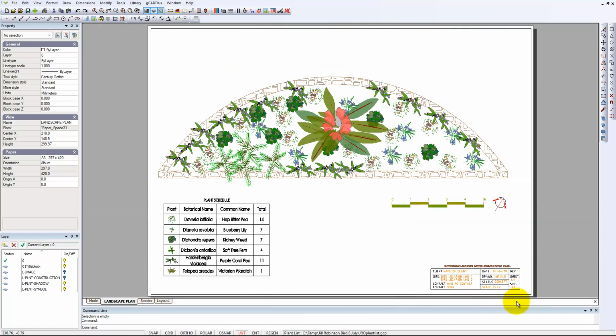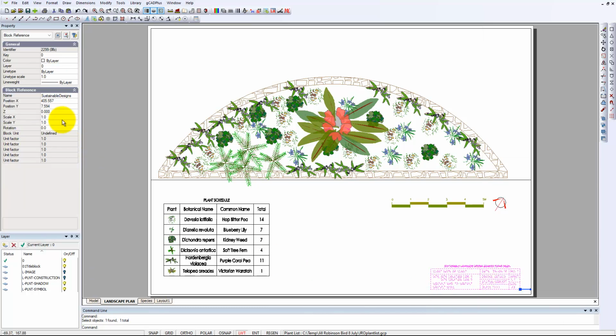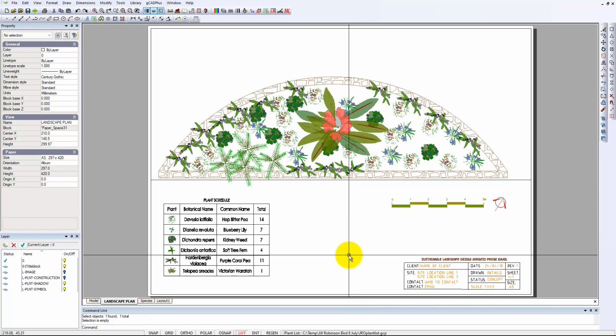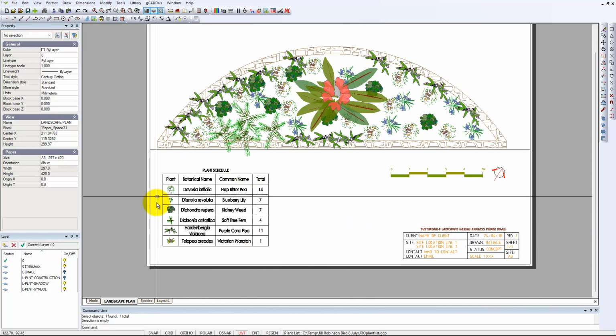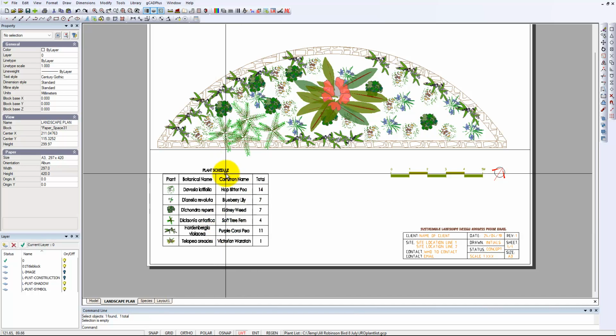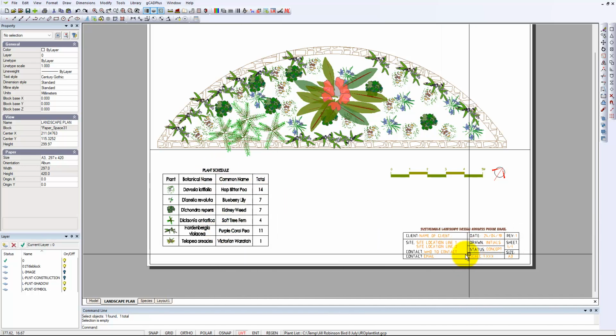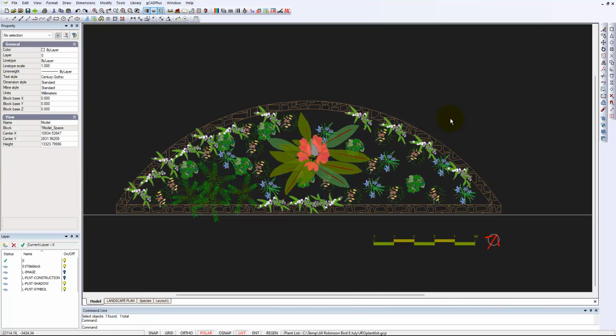If you think that's a little small, because it's a block, you can say, well, I'm going to take that and make the size of it 1.3 for the sake of argument, and the X and Y would both be slightly increased. So you could argue that looks a little better. You wouldn't want it the same text height as the plant schedule, but you certainly want it readable.